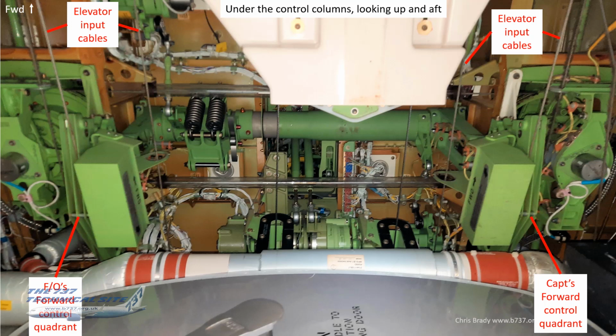Looking at the left-hand side, on the inboard section, the elevator input cable goes forward, around a pulley, and then comes back the other side of the weight and goes aft down the cabin. On the outboard section of the quadrant, there's a second cable, and that just runs straight aft. It's a little difficult to see on these photos, but it is there. Perhaps if you pause the video and zoom in, you might be able to see it.